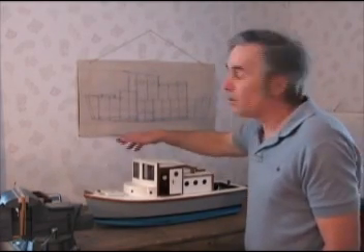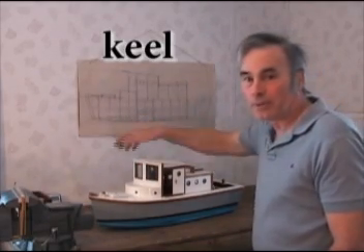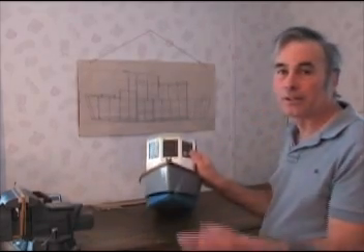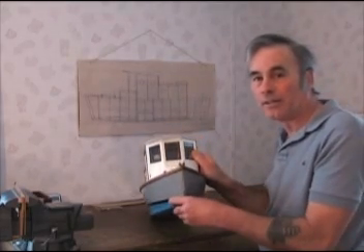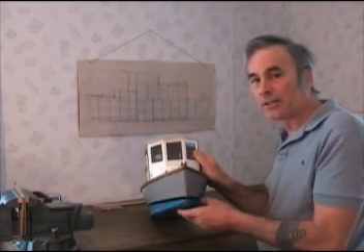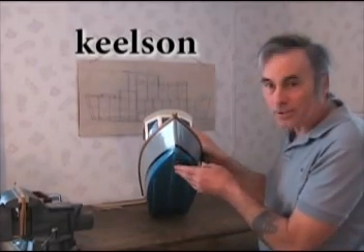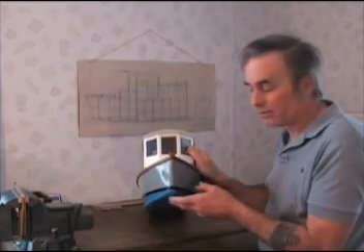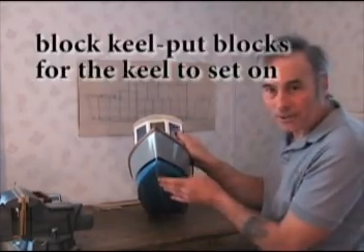And the backbone of the boat is made up of the keel. The keel is the main backbone piece that runs down the center of the boat, in the middle of the boat. This boat will have a two-piece keel, what they call a composite keel. There's a piece on the inside, which in a plank boat would be called a keelson, which is a 2x8, which is the main keel. And this keel runner I'm putting on the outside also acts as part of the keel. So if they tell you in the boatyard, go block the keel, this is where you block.